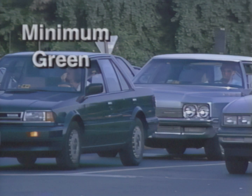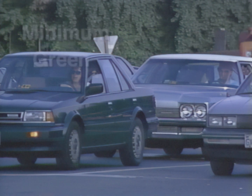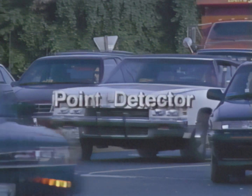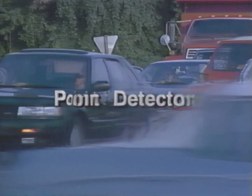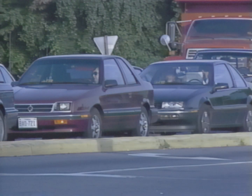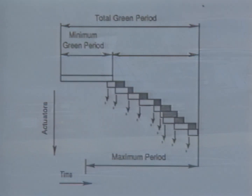The minimum green interval is the amount of time a detector allows for a stopped vehicle to accelerate and move into the intersection. When a type of point detector, such as a 6x6-foot loop detector, is used, the minimum green interval allows a vehicle stopped between the detection point and the stop line to comfortably move into the intersection. Presence detectors with loops ending at the stop line require a different timing approach. In this situation, the minimum green interval can range from 0 seconds for a turn lane requiring a quick response to a longer period of time for straight-through vehicle movements.